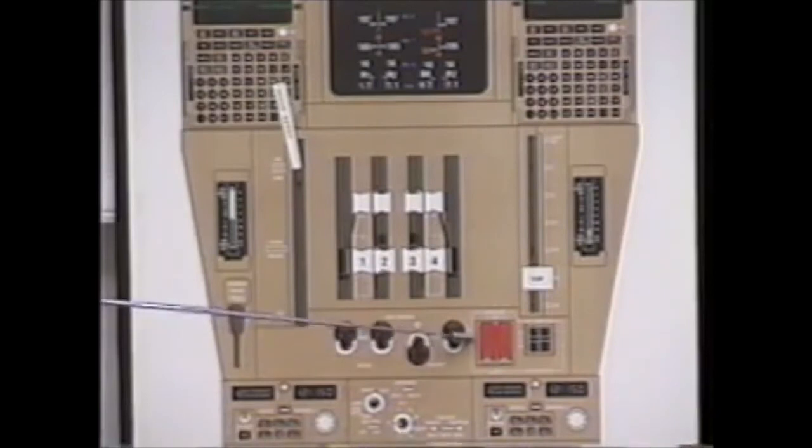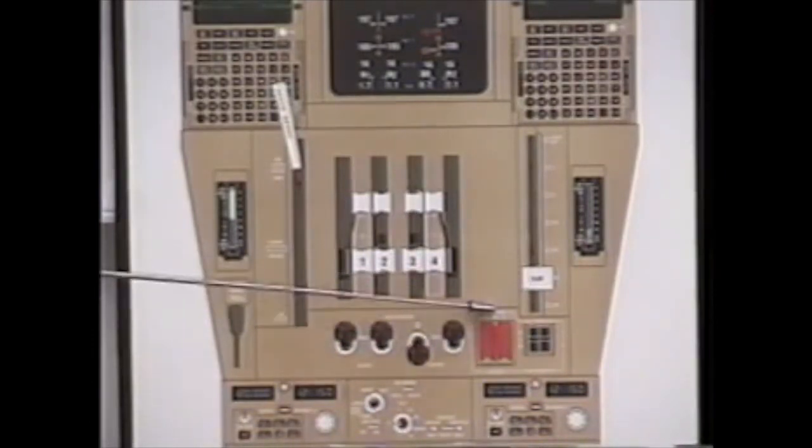The difference between auto and on. In the automatic position, the stabilizer trim, when it detects movement, will look for an input signal from an autopilot, from a yoke switch, or from the alternate switch. If it does not find an input signal, it will automatically shut off all hydraulic fluid to the stabilizer. If the switch was in the on position and the stab moved, the system does not look for an input signal, and thus an unscheduled trim is allowed to continue.